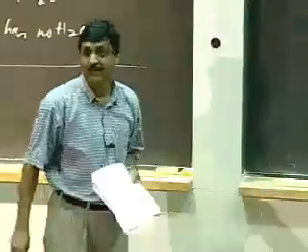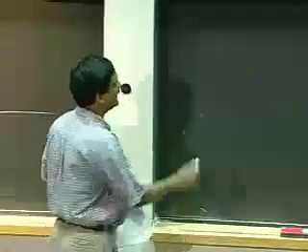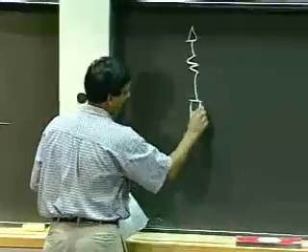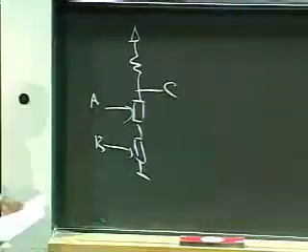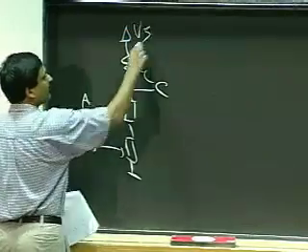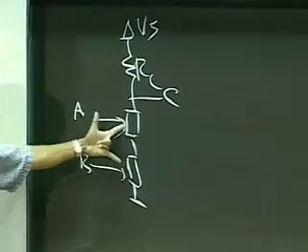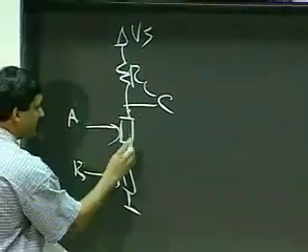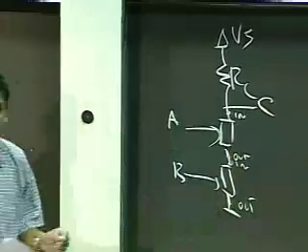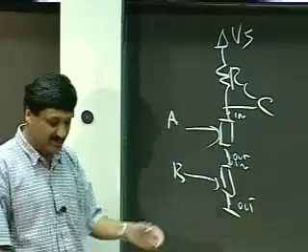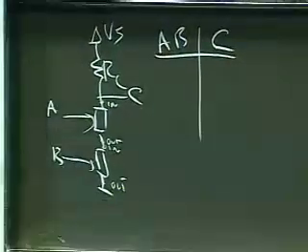So let's look at, that's an inverter. Let's look at how we can build other forms of gates. So to build another gate, how about this pattern? If I build a pattern like this with A and B coming in here, and I put 2 switches with their inputs in and out. So 2 switches in series. Let's write down the truth table for what this looks like.